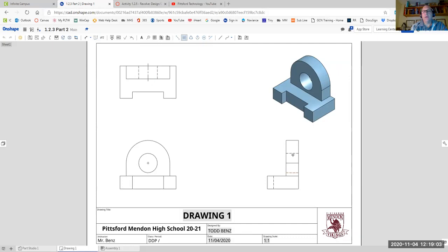And same down here. Now this one is actually covered up by the object line. The object line precedes any hidden line or center line. So that will be on top. So that's why you can't see it, but you can see that the little pieces stick out on the ends. I'm not going to have to do one here because that's actually not a round hole. That's actually a square. So I don't have to do a center line down here.